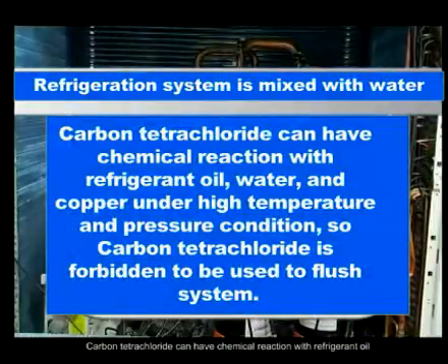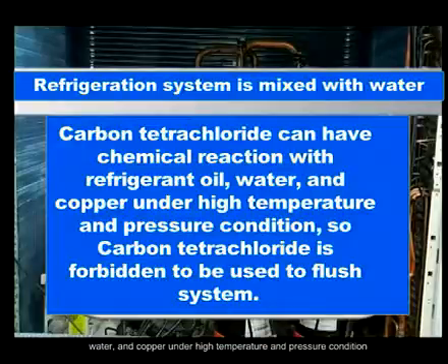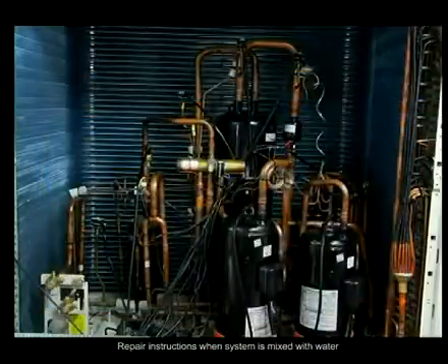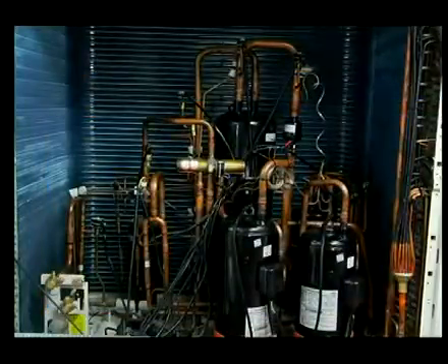Carbon tetrachloride can have chemical reaction with refrigerant oil, water, and copper under high temperature and pressure condition. So, carbon tetrachloride is forbidden to be used to flush system. Repair instructions when system is mixed with water.